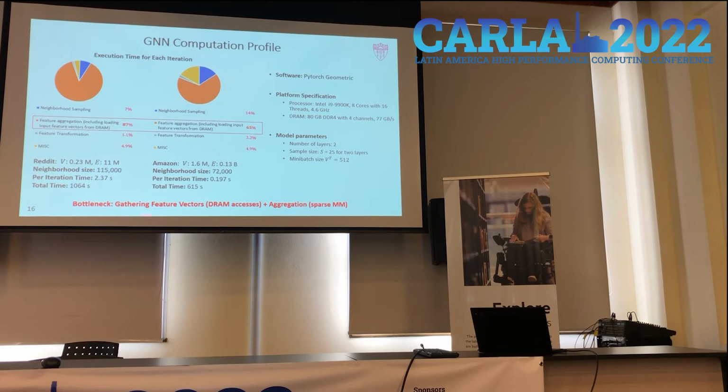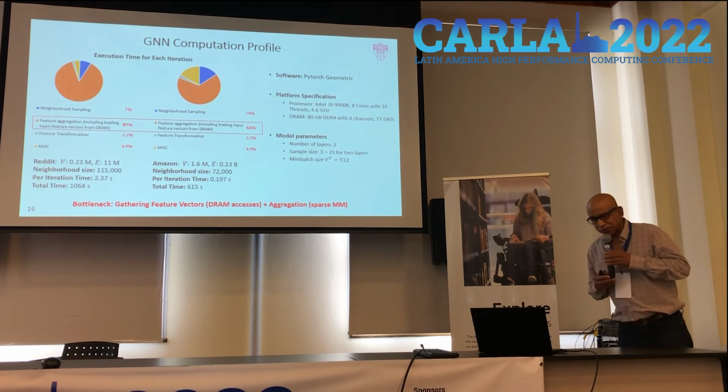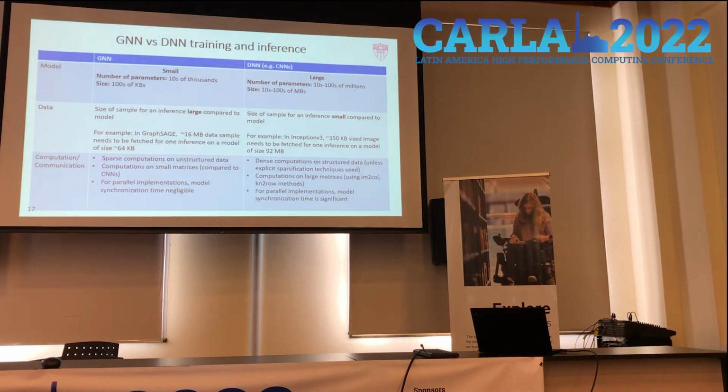That is the bottom line here: the DRAM accesses and communication between the FPGAs and the processor are where the real bottlenecks are. So if you can handle that problem, you can get high performance, scalable implementations for these kinds of applications.